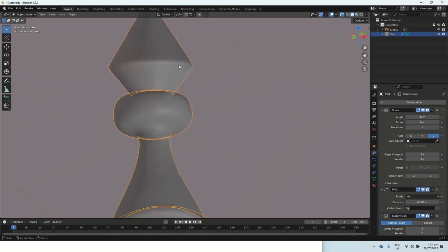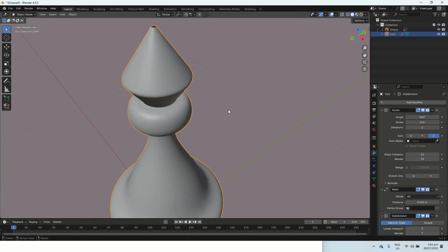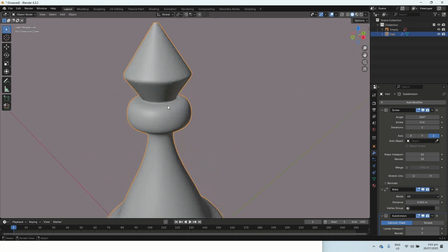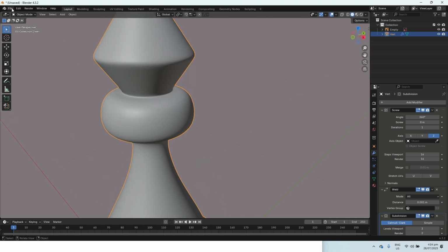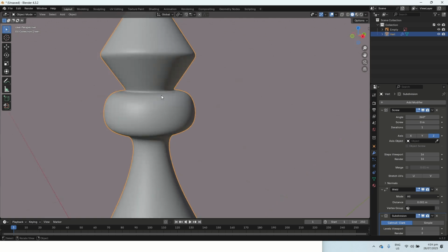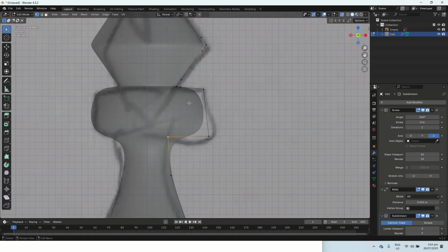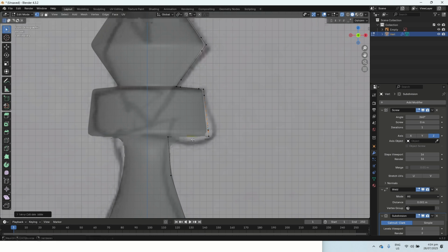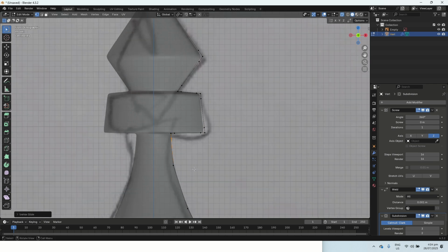So in order for my creases to work, I'd need to actually apply all of these modifiers. And as we discussed with the non-destructive workflow thing, that is an option, but it'll be hard to come back to this point where it's very easily editable once I've done that, okay? So I think for now, we'll just stick to the Control R method. So Control R, adding a new vertice, and then Shift V to drag it along and put it where we want it. We can look at creases when we look at the rook next week.